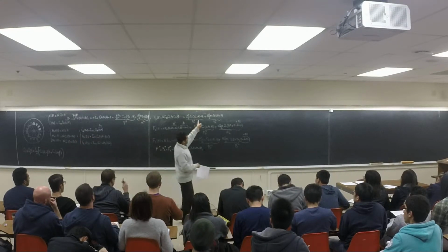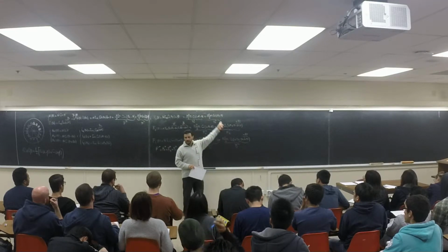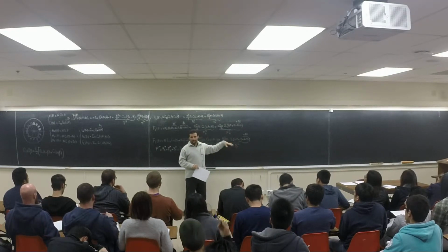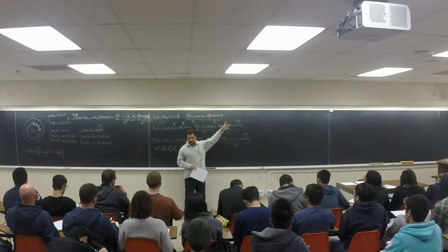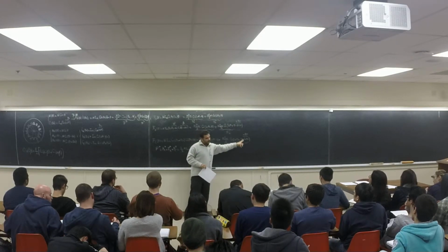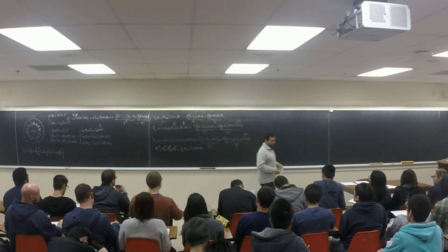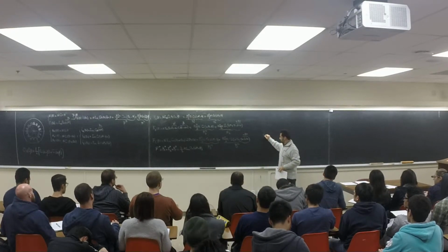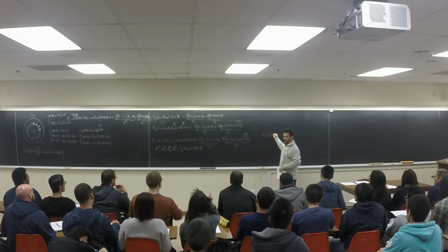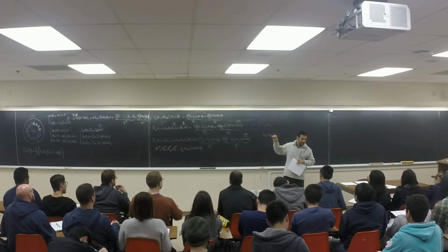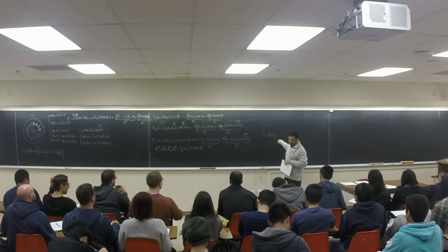This is the definition of a balanced three-phase system, right? 0, 120, minus 120. If in the three-phase system I had a balanced system, how much was VA plus VB plus VC? Or IA plus IB plus IC, it's going to be 0, right? For any balanced three-phase system, all added together is going to be 0.